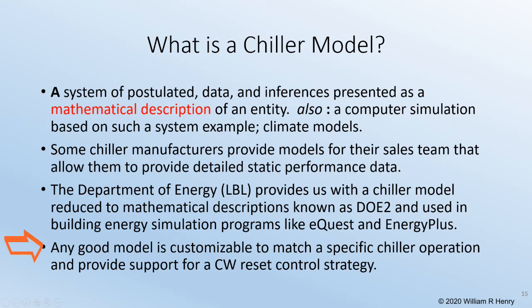Any good model can be programmed to match a specific chiller to provide optimal condenser water temperatures at various loads and to develop a condenser water control algorithm for that chiller. On the other hand, a real-time model uses real-time inputs like load and water temperatures and runs the model in a PLC or other device coincident with the chiller's operation. Since it is nearly impossible to repeat a given load and weather conditions, this makes real-time prediction a valuable concept. In the next slide, I'll show examples of a couple different models.